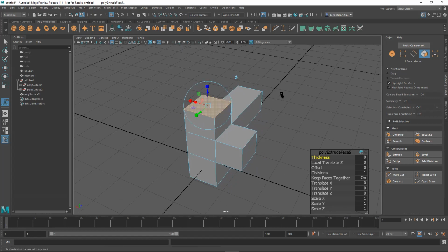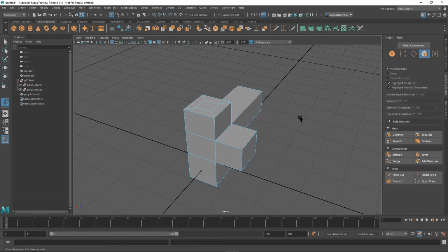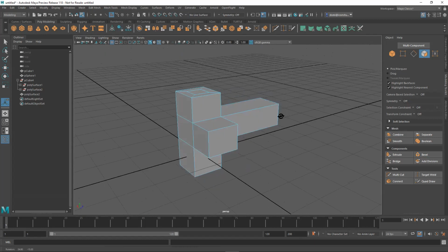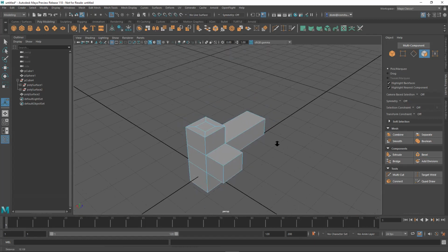You can scale with extrude, not only pulling. To get the scaling, just as with moving, the boxes mean scaling in your transform tools. So just click on any one of them, and now you've shifted into the scale mode. Now, you can scale in a direction, but the key thing to do is to pick the center scale cube there, press on it, then start scaling on that. Now, this has done something very interesting, and you will use this a lot, I can promise you, in Maya.